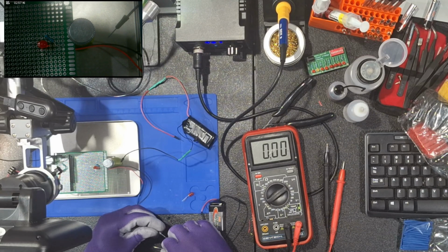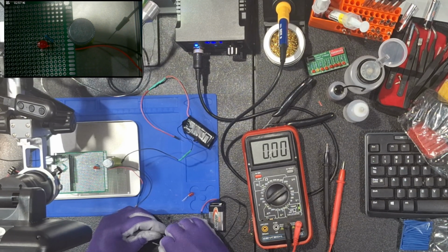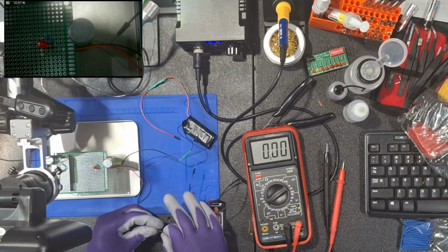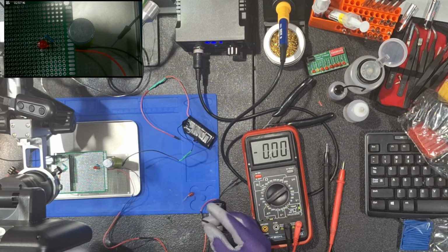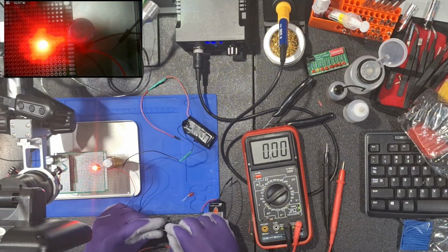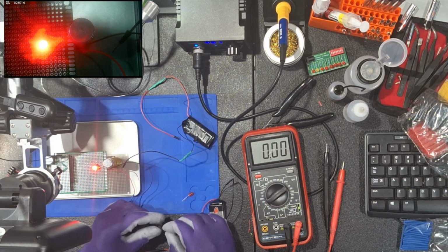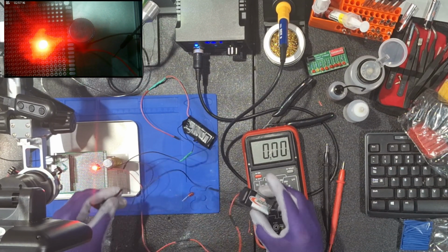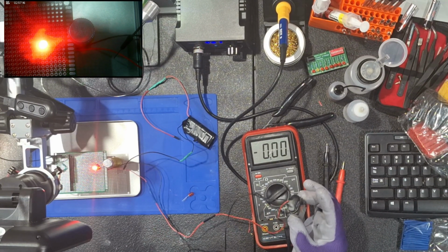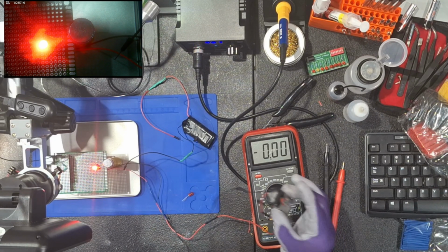Ready to connect? Alright, let's do it then. We have a red wire for positive, the black wire for negative. I'm going to connect the black wire now. Black to black. Boom, there we go. We have light, continuous light. It's not flickering, not burning up, just staying on continuously. So thanks to the resistor, we can use this 9 volt battery to power this LED without burning it up.